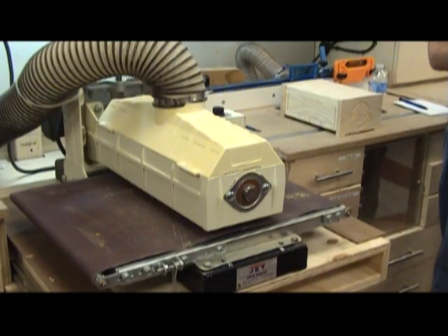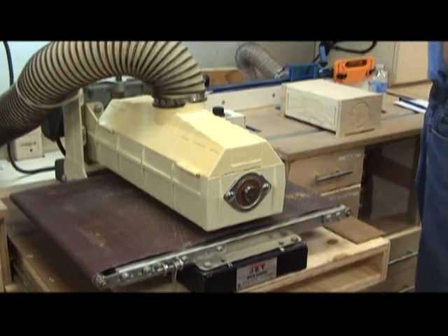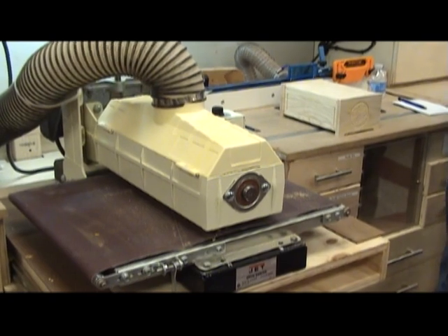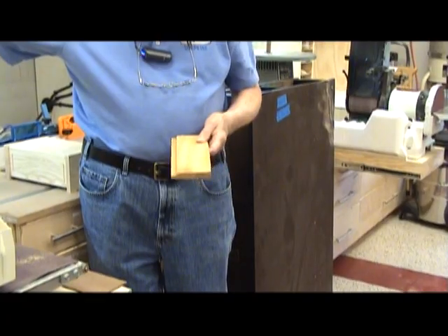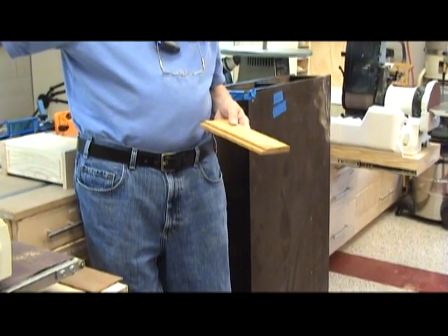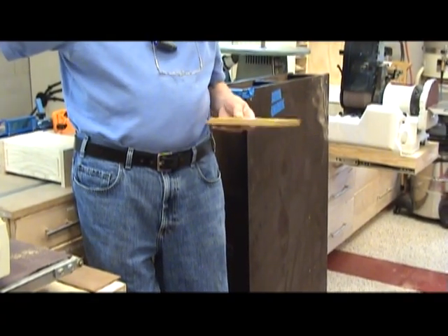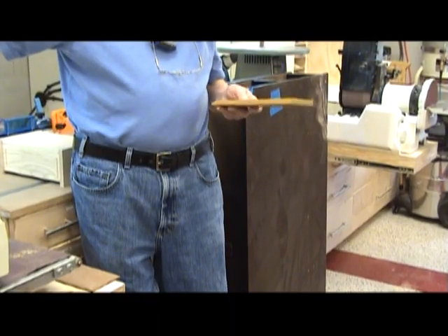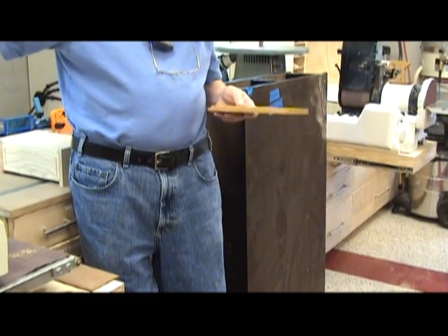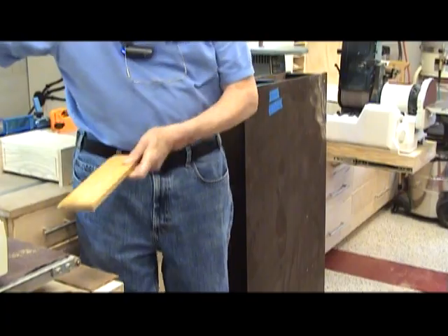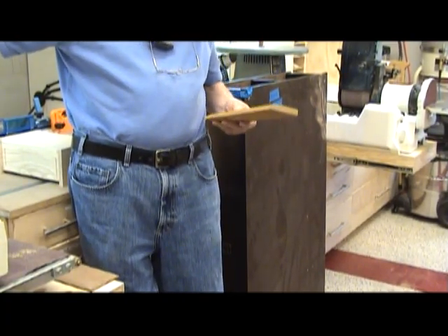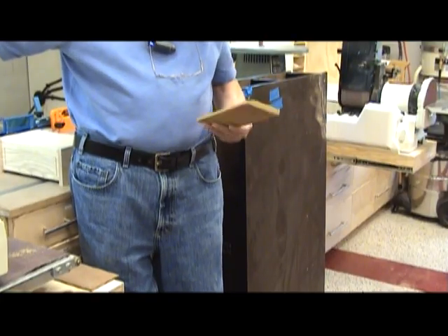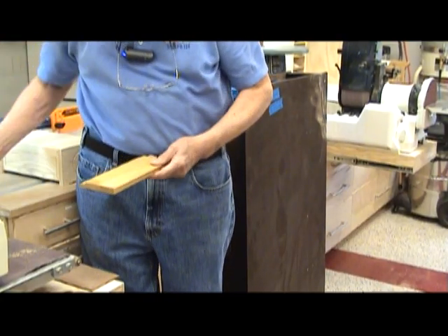Just gently find where the drum is touching the surface of the wood. At this point, go down a quarter of a turn at a time until you zero in on the thickness you need. And it's going to take 5, maybe 7 passes at that rate to get it down.